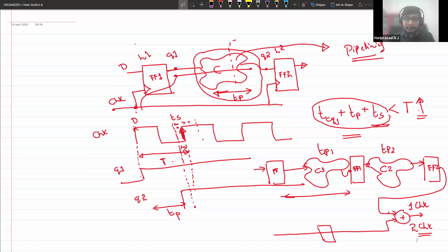When I consult for startups on their design reviews, I usually see that there is no timing violation and simulation is working fine, but when they put it on the board, it is not working. Then I have to keep debugging what kind of constraints they put. Wherever they see a timing violation, they keep putting false path or multi-cycle path. By default, the tool will ignore that path and not analyze the timing, showing timing clean with high positive slack. But when I keep removing these constraints, I start seeing the timing violation.